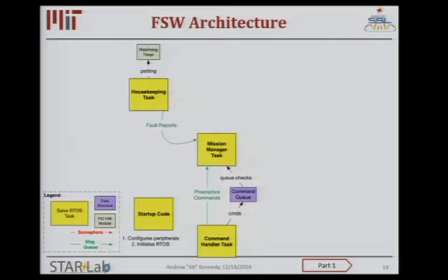The housekeeping task there at the top left just collects telemetry and packetizes that and gets it ready for downlinking to the ground, as well as assesses that telemetry and looks for faults to see if the watchdog timer needs to be petted, as it were.